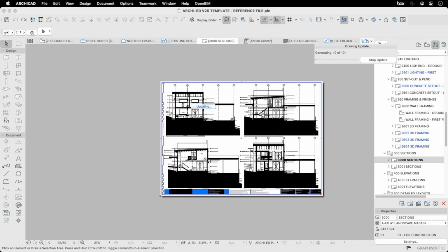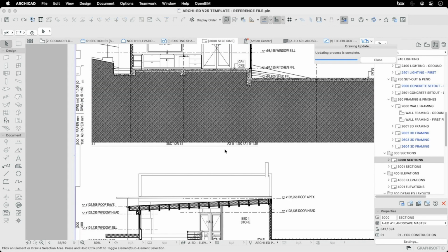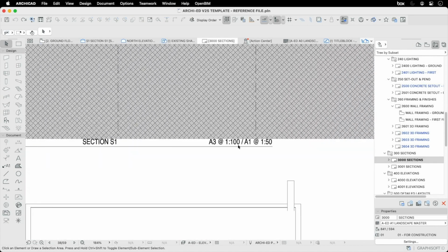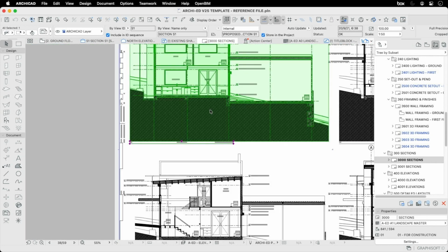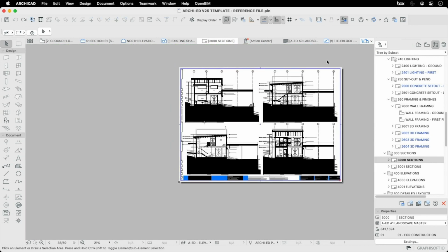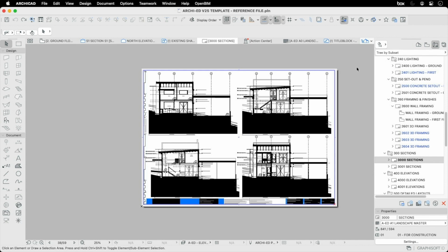Now, the intention of how this works is that, generally speaking, the majority of my drawings for residential purposes will be at 1 to 50. So I'll aim to achieve floor plans, sections, and elevations all at 1 to 50 on an A1 drawing, which means that when it's output on an A3 drawing, that equates to 1 to 100. I mentioned both of these. I actually don't do printing. I try to stay pretty much paperless in my office, but that means if it's being sent out to a builder, if they want to print it, then they understand the ratio and relationship of the scale.